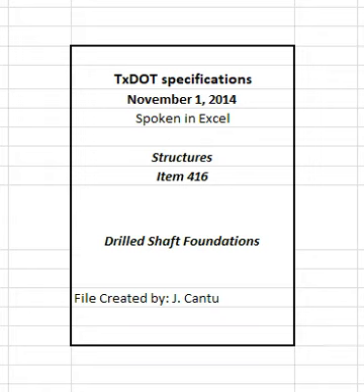When trial shafts are required, delay start of production shafts until successful completion of trial shafts. 4. Measurement. 4.1 Drilled shaft. Drilled shaft foundations will be measured by the foot to the bottom of the shaft.